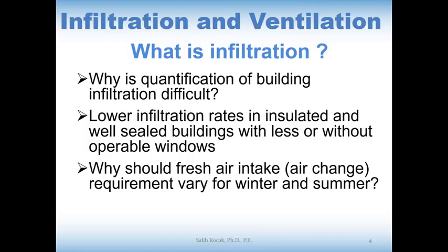And this is really important, because most of the calculations we are going to be doing will require this and what the authorities are suggesting. During winter and summer, the fresh air intake is different, and winter air changes are about 50% larger than summer. Okay, this is really important.